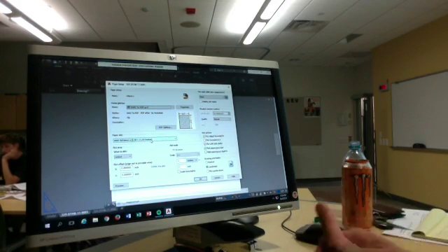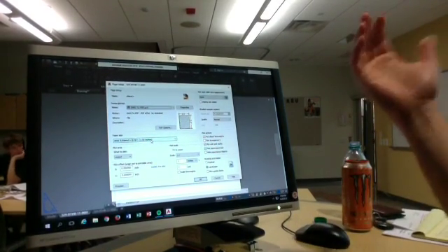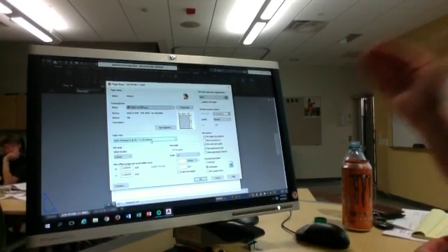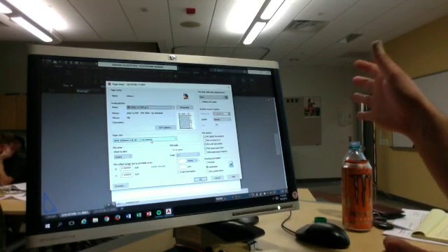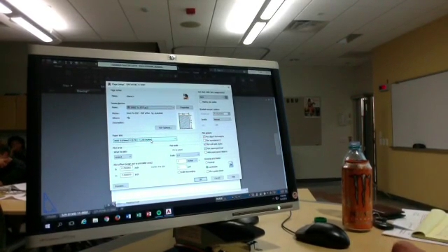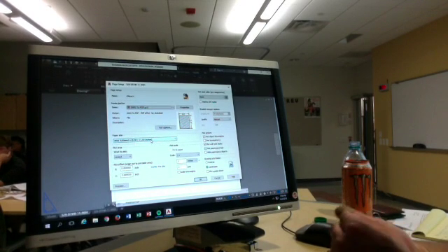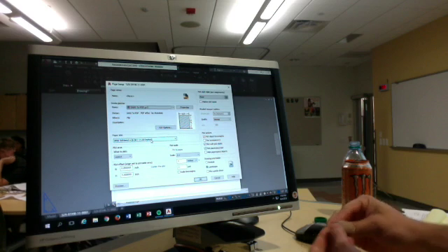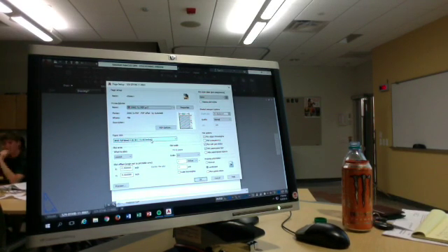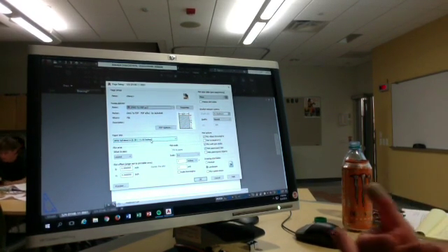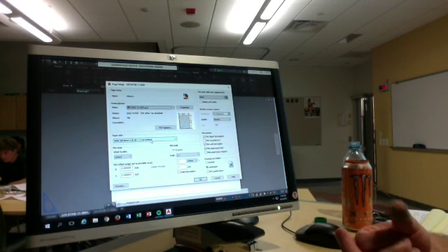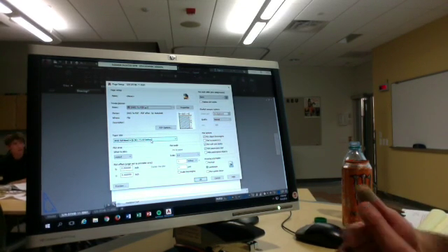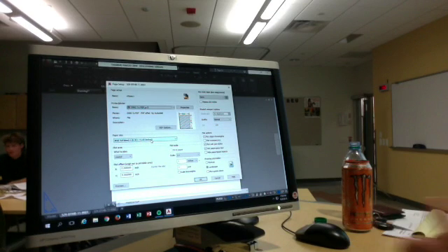What's cool is that DWG to PDF has literally every single page size imaginable listed in it. But if you're using, let's say, a KIP printer, like we have a 7170 at work, it'll list only the page sizes that it's capable of printing. That's pre-built into the printer, so we can do 24 by 36 or 36 by 48 on it. Whereas when we go to our Ricoh, it specifically lists 11 by 17 and 8.5 by 11.